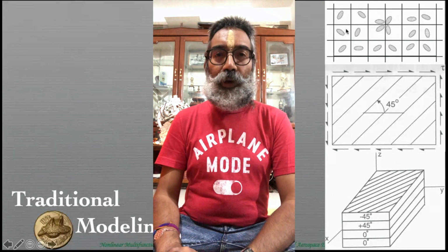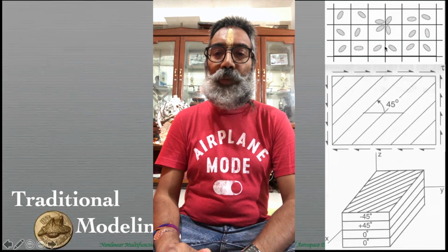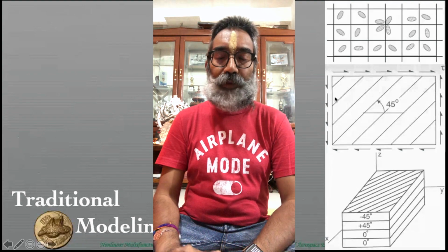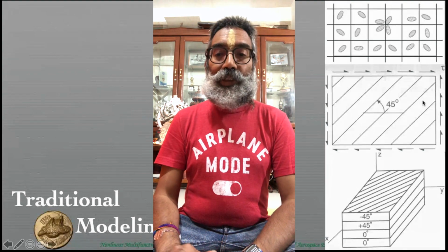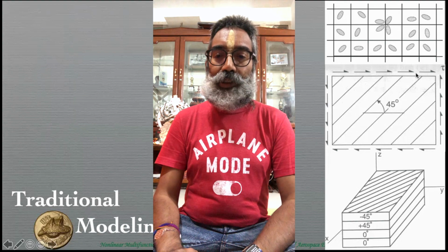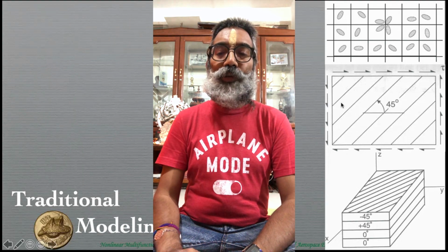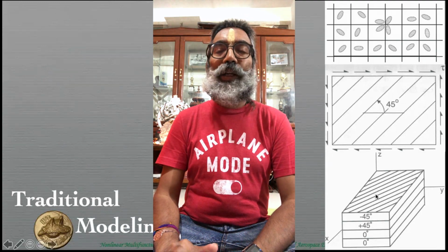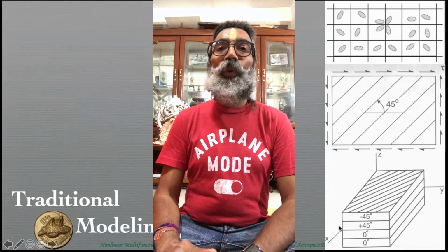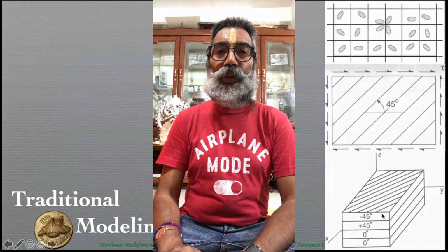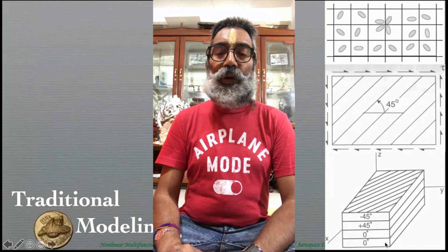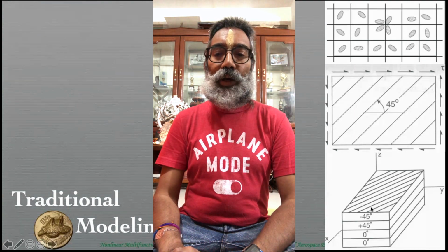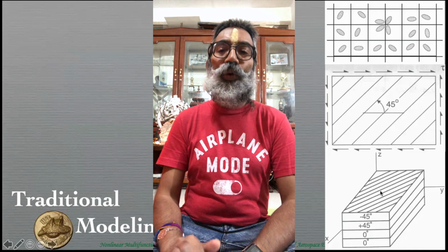But for this course, most of what we will do will be at the micro level, and we'll be mostly done with that in today's class itself. One of the things that a large number of classes will be focused on is the next level, what we call mesomechanics at the lamina level, where a single layer is taken up. In a laminate, most of the classes will be devoted to the laminate level, where a particular stacking sequence will be taken up, and we will look at how that can be analyzed based on information flowing from this way.